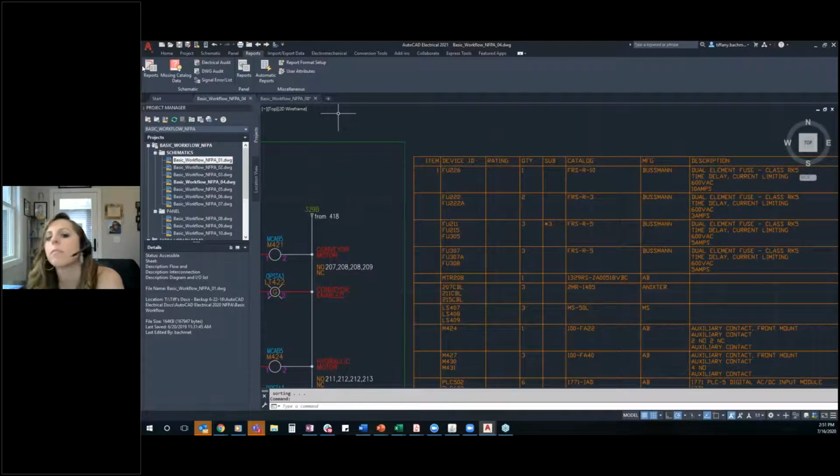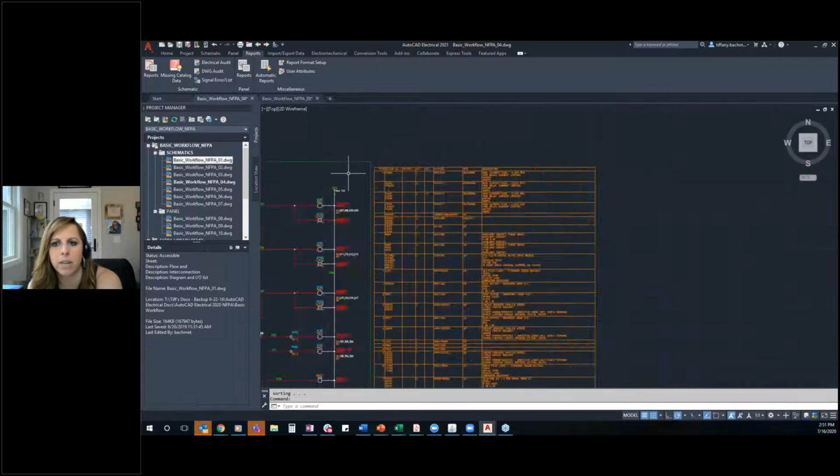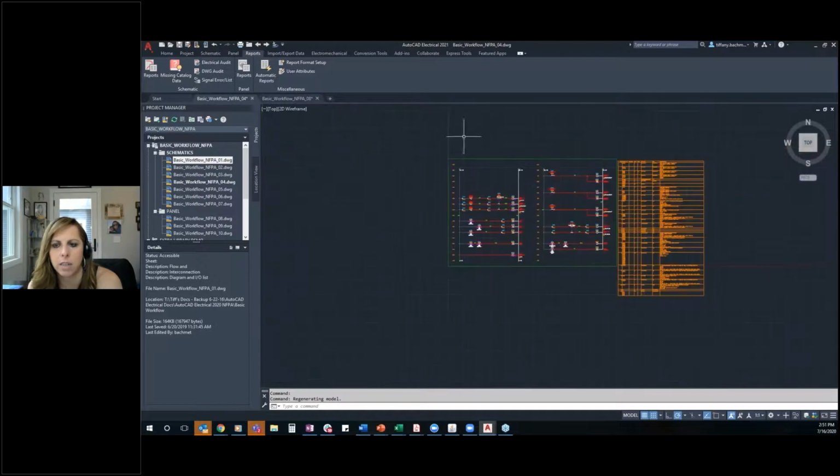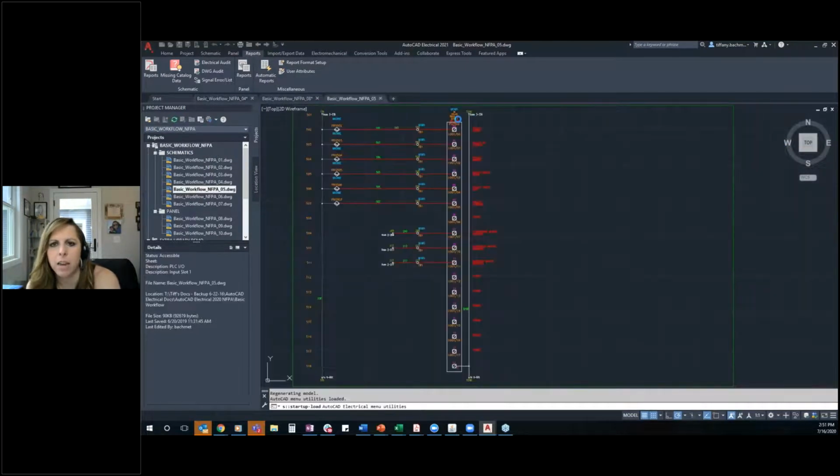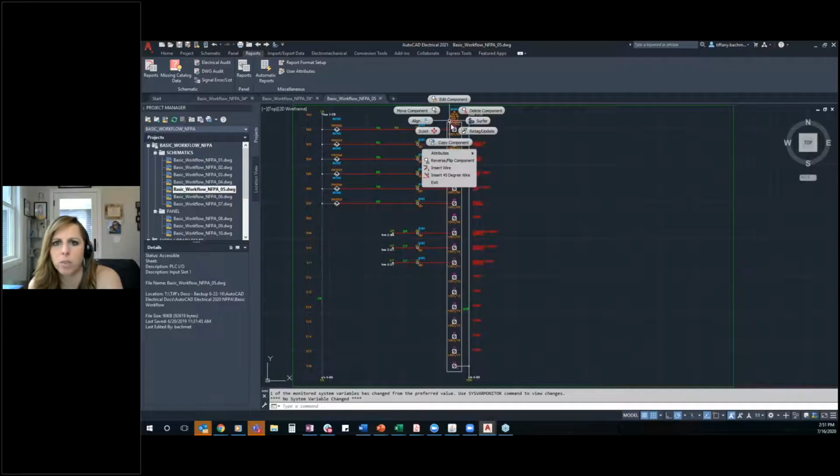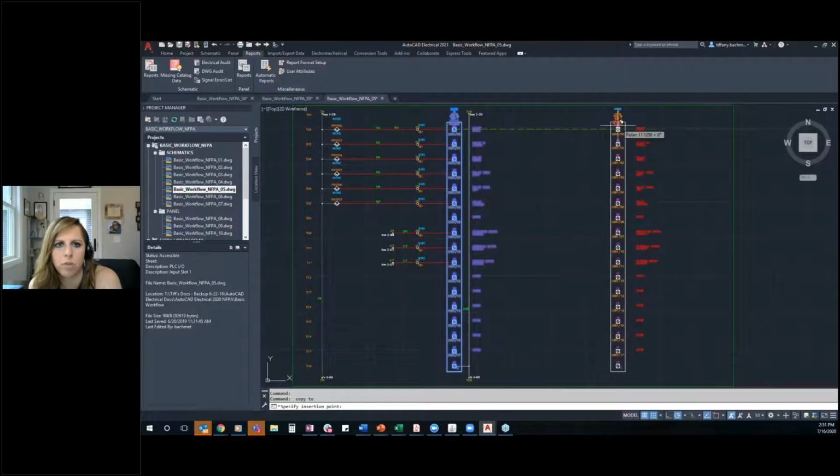All right, good. From Jeffrey, can we duplicate a parametric PLC and rename it? Can you duplicate it? Yeah, do you mean can you copy and paste it as another device? Like, can you use the copy device? I think that's your question. You can, like if I wanted to copy this and paste it elsewhere, you can absolutely use a copy component and move it over, and then it will automatically launch you to rename it.